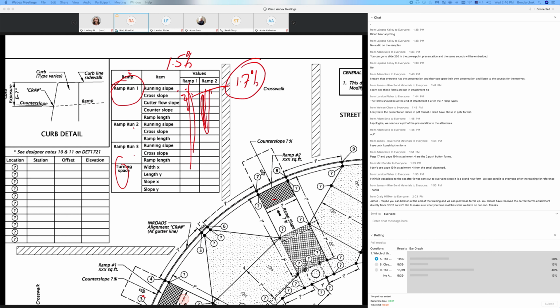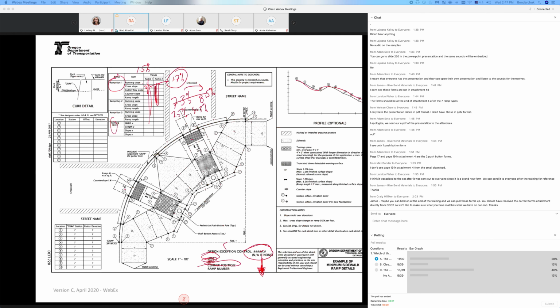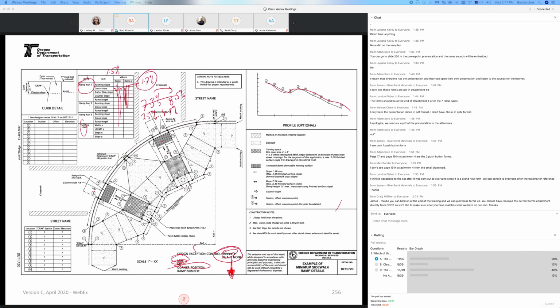You look for that. Similarly, designers design to 7.3%. Contractor have a tolerance up to, no, I'm sorry, take this back, 7.5 and 8.3%. So if you see here 7.6, that means there's a design exception, and then you find that. So that's a QQ if there's a design exception. If you see numbers here, and there's a design exception, could be for dimensions too, not only for the slope.